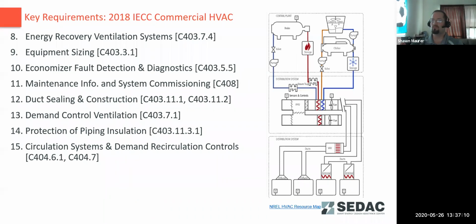I'm going to answer one more here, and we'll try to get to some more of these towards the end of the presentation. How are curtain wall assemblies unique in meeting thermal requirements? Curtain wall assemblies fall under the U factor and solar heat gain coefficient requirements for window assemblies.